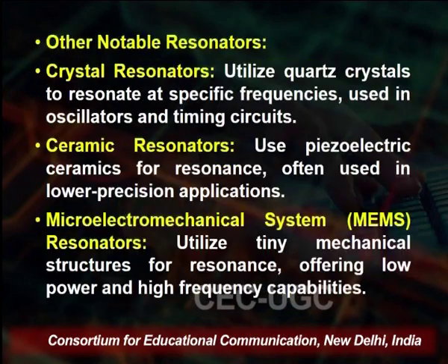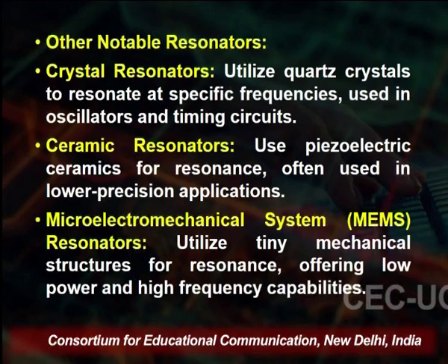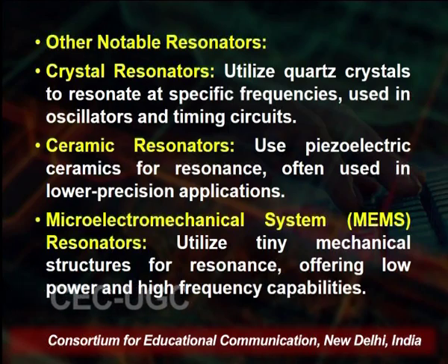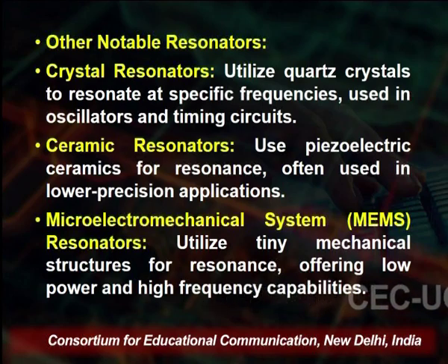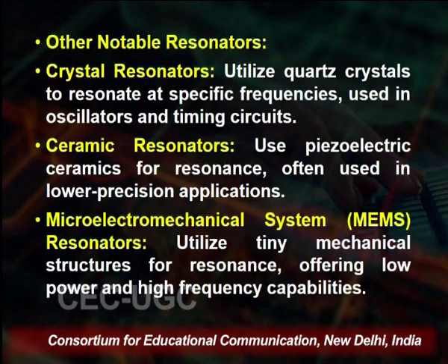Other notable resonators are the crystal resonator, which, as the name suggests, uses crystals, the quartz crystals, to resonate at a specific frequency, used in oscillators and timing circuits. In this category we also have the ceramic resonator, which uses piezoelectric ceramics for resonance, often used in lower precision applications. Then we have the micro electromechanical system resonator, that is a MEMS resonator.